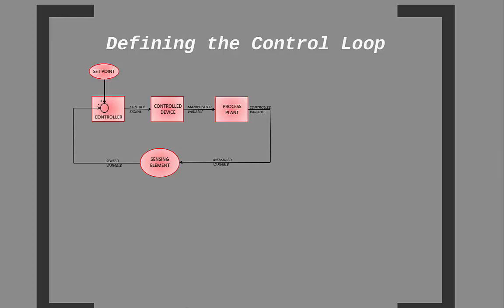Now, all of this control theory we are discussing thus far can apply not only to cars, but to anything, including HVAC systems. So let's look at an HVAC example and identify the parts of the closed loop. This diagram here is a very common control configuration in HVAC systems, as we will see repeatedly in the weeks ahead. Relatively cool air is brought across a heating coil.